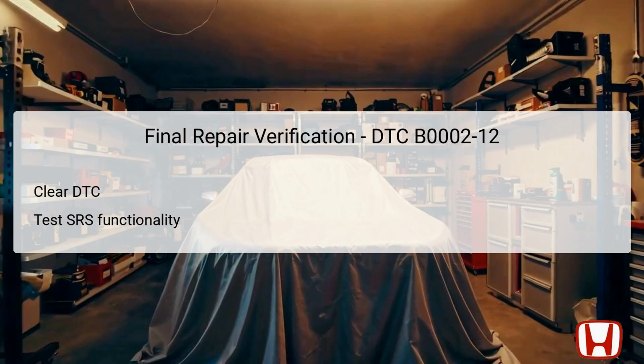Following this, the technician should test the SRS functionality to ensure that all airbags, particularly the driver's airbag, deploy correctly in case of a collision. It's essential to validate that no warning lights remain illuminated on the dashboard. This comprehensive approach ensures that both the airbag components and the system itself are fully operational, thereby increasing vehicle safety.